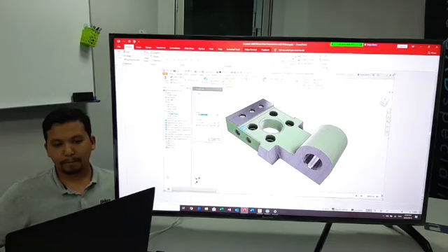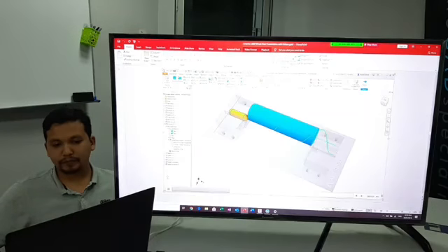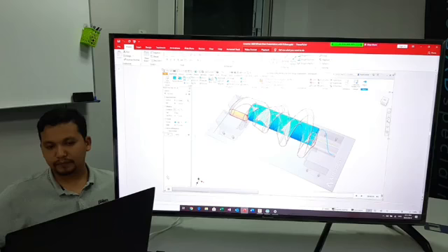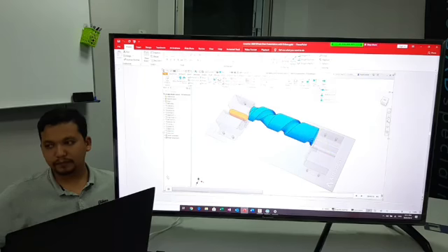In the relationship dialog box, sketch blocks now display in relation to their consumed features. The sweep command has also been improved with the ability to add or remove geometry by sweeping a solid along a path. Select a solid to act as your tool body and a path to sweep along. Optionally, choose an orientation and twist angle to alter the course of the body as it sweeps along the path.